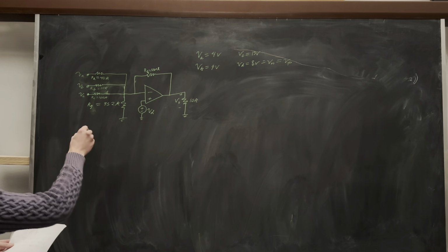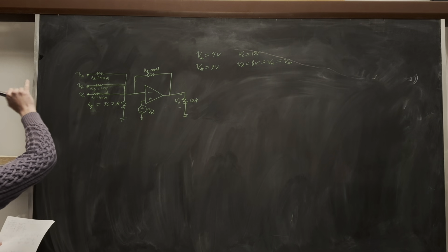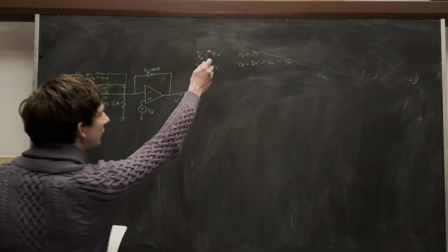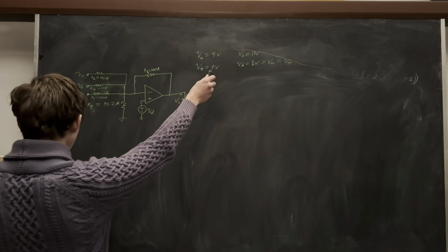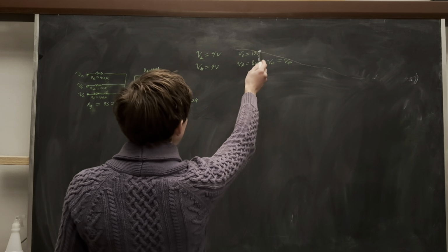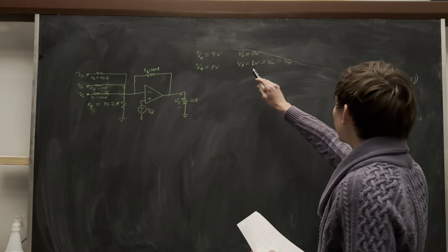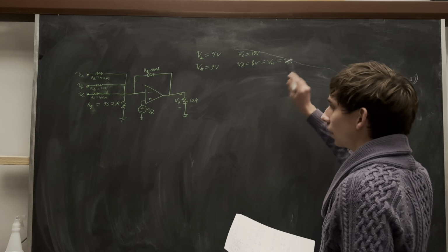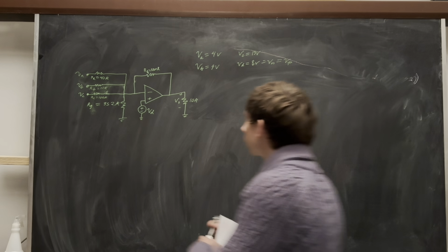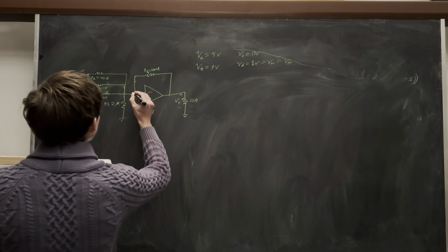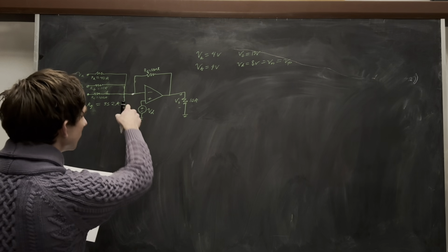So, start off, we have these 3 input voltage sources. Those are given. VA is 4 volts, VB is 9 volts, VC is 13 volts, VD down here is 8 volts, which is the same as VN and VP, since we assume it's ideal. If we do KCL at this node, we'll be able to get V out.